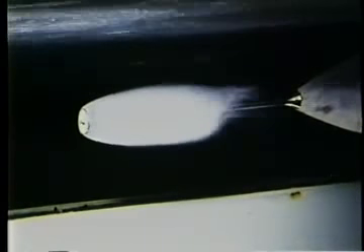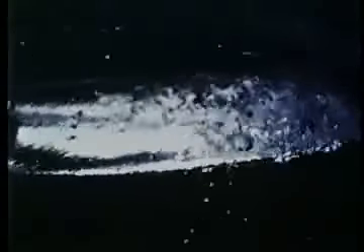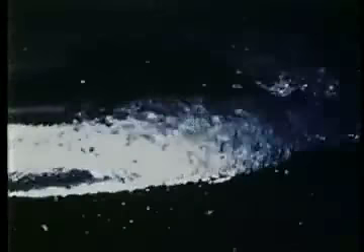With high-speed photography, we can see more of the details of this complex flow. The flow at the end of the cavity re-enters and moves upstream. This re-entrant flow is illustrated more clearly in the cavity trailing our supercavitating hydrofoil. Re-entrant flow is characteristic of such cavity flows. The momentum flux in the reentrant jet is equal to the pressure drag of the body. The jet kinetic energy is dissipated.